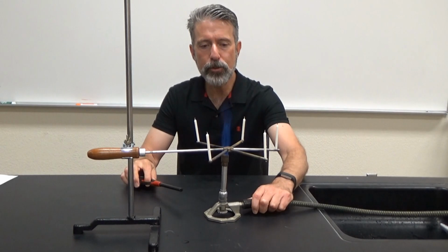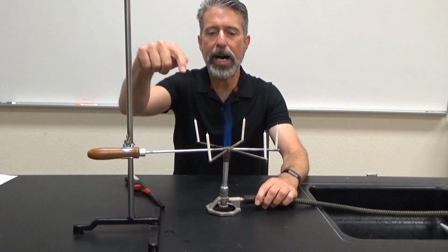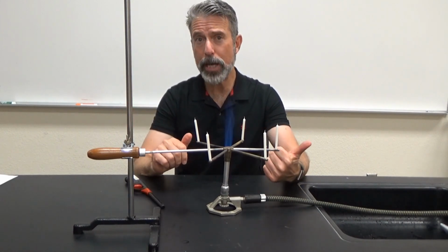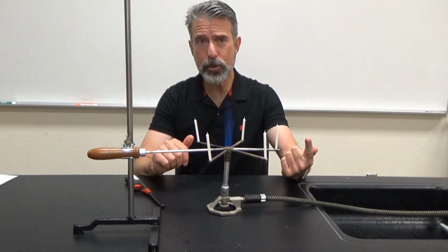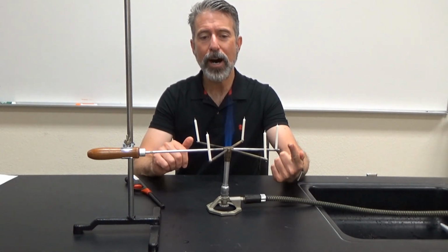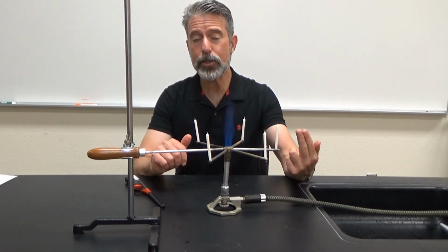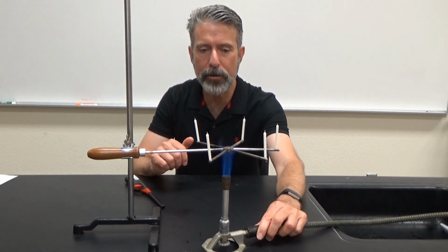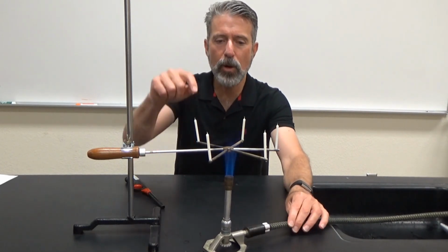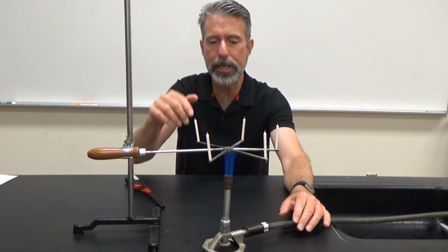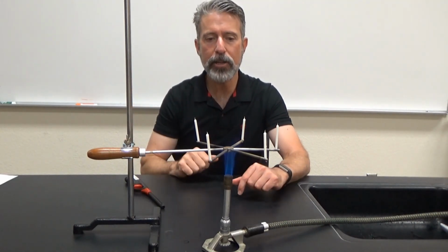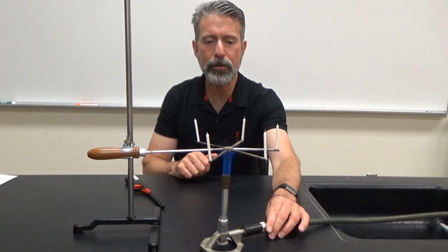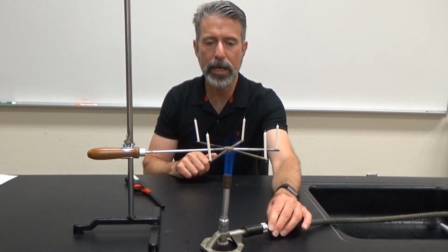So let me get this lid and I'll explain a little bit about the setup here. You'll see that we have 5 different rods. Think of them as slabs. They all have the same length, and they all have the same cross-sectional area. They are all going to be subjected to the same temperature gradient. By placing this Bunsen burner here in the middle, the ends of the rods that are near the Bunsen burner will be at the same high temperature. The other ends will be at room temperature. The only thing different about these rods is the material they're made out of, and therefore their thermal conductivity constant.